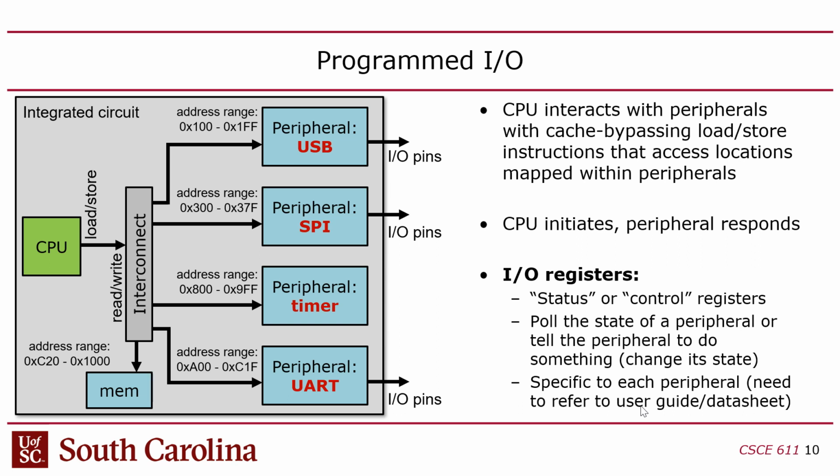But basically all it does is it allows you to build an interconnect, where the CPU has one memory interface. It only has one interface that has an address, data, and read or write control lines. But somehow you have to broadcast that out to all your peripherals, and that broadcast is performed through this interconnect. And the interconnect is built with a certain on-chip network technology in mind, like AXI, right?